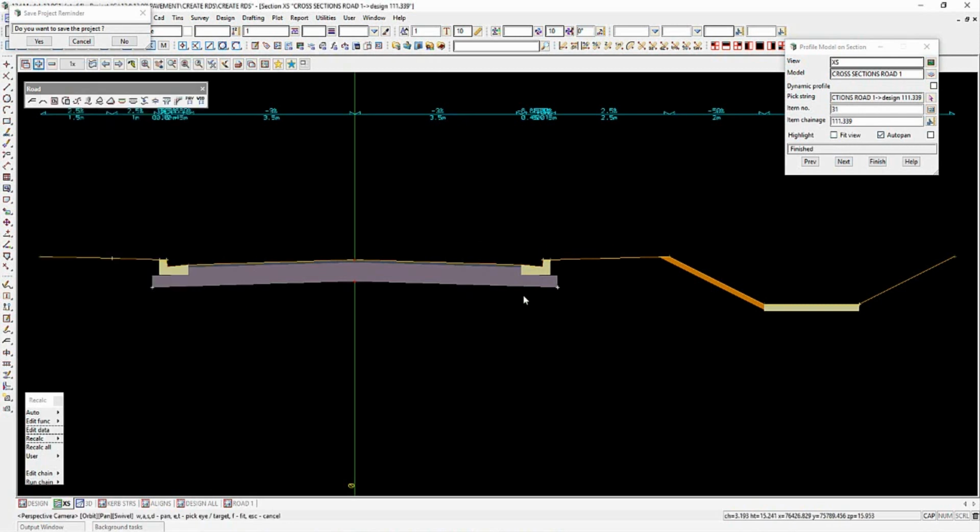So there's a string here, some there, and some there. These are all the strings that you need to create the subgrade triangulation. You can do subgrade strings for every layer in the job except for the curb in this case.